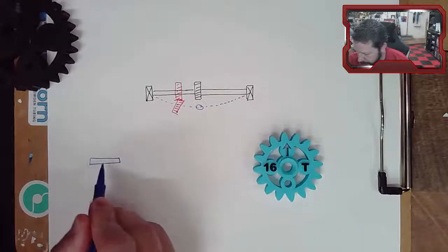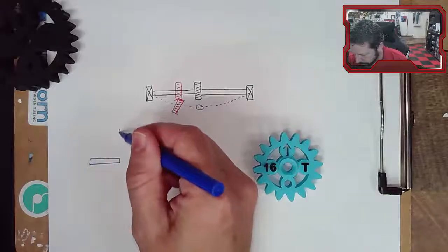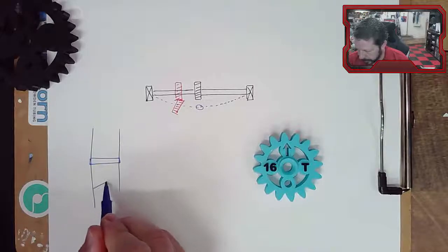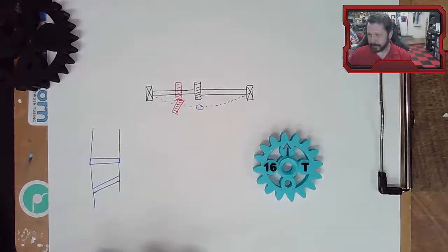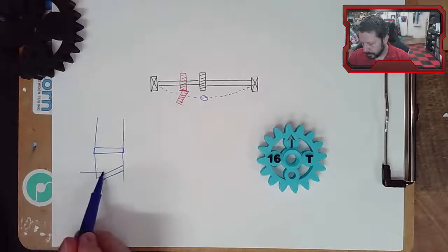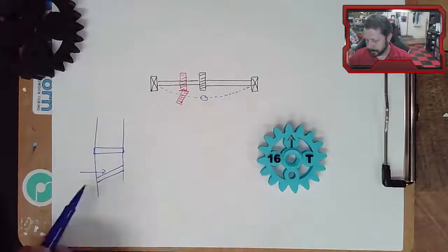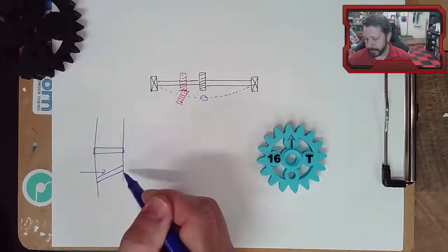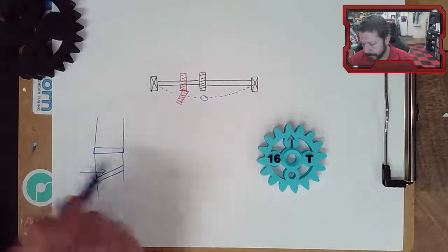So instead of having them the same width for the gear, you can angle them, right? Now I get a little bit more surface area over here, but my gear teeth are angled, which induces a thrust load. To counteract that thrust load, you might have a collar back here or a shoulder or something so it just can't move.